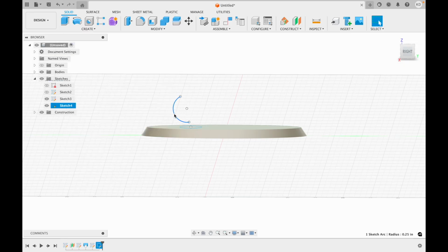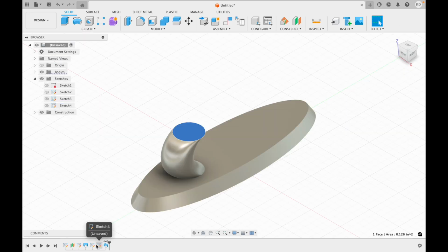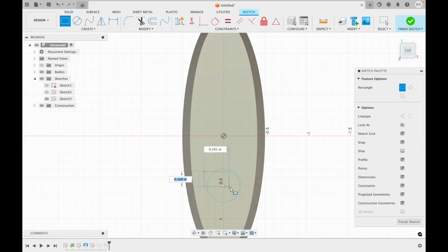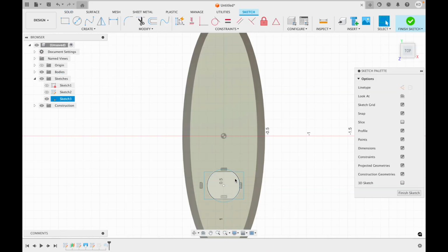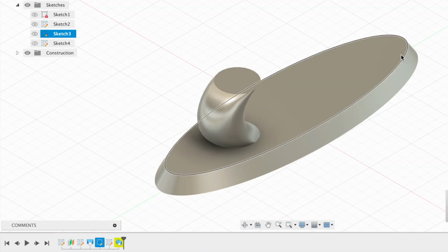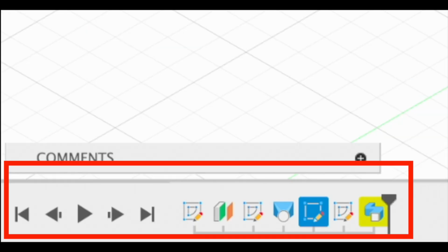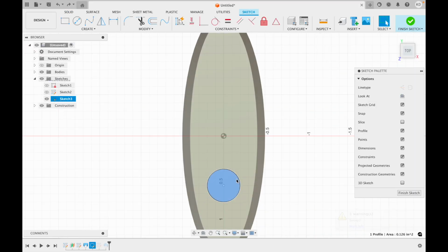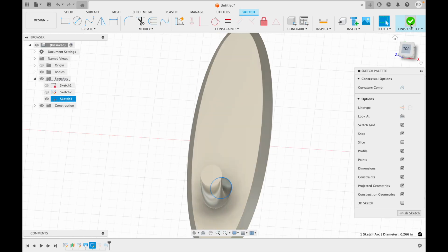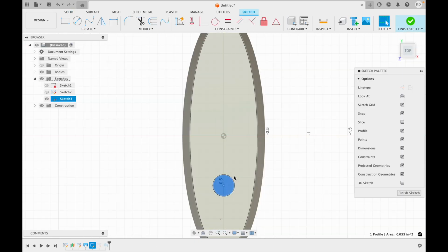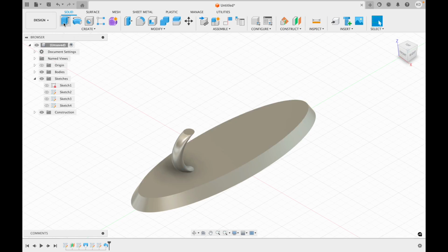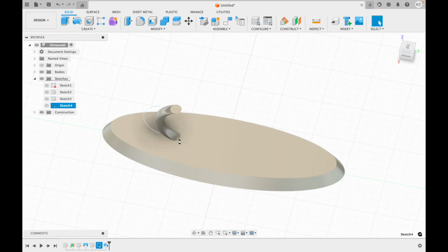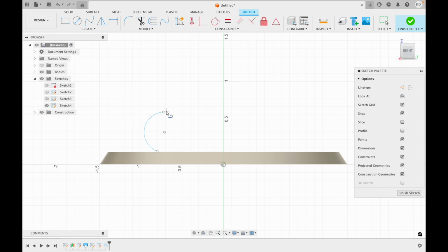Now, after I fix it, I'm like, ooh, let me mess around with this. And I'm thinking, what if I change the geometry? You're going to see in that timeline that it's yellow, which means that Fusion didn't like that. So what you do when you have the yellow timeline thing is you click on it, and it tells you what it doesn't like. It just brings you back there, though. And then you fix it, and then you can tweak it, and boom, you have the proper function. Your timeline's happy because nothing's yellow, and yeah.